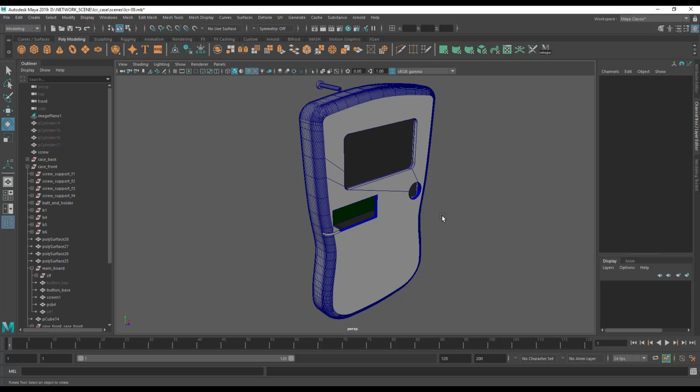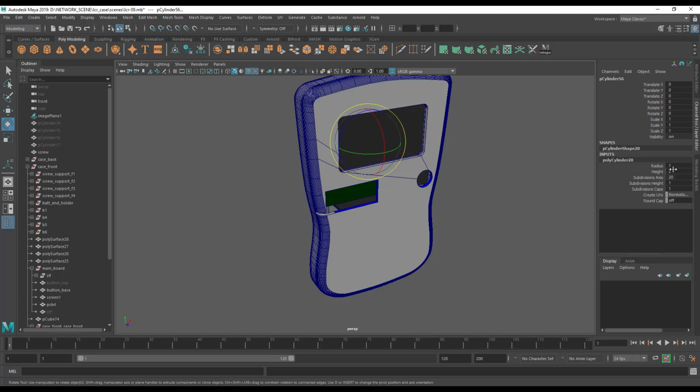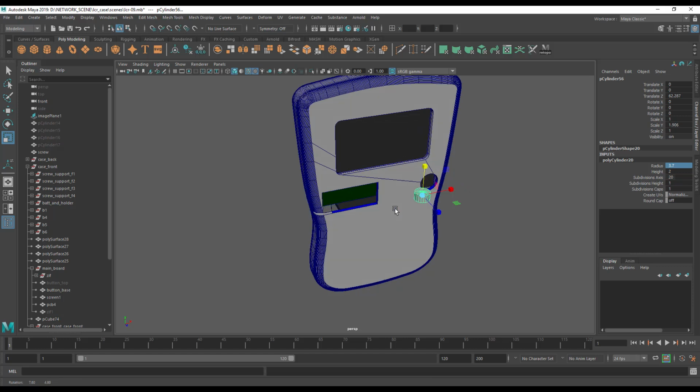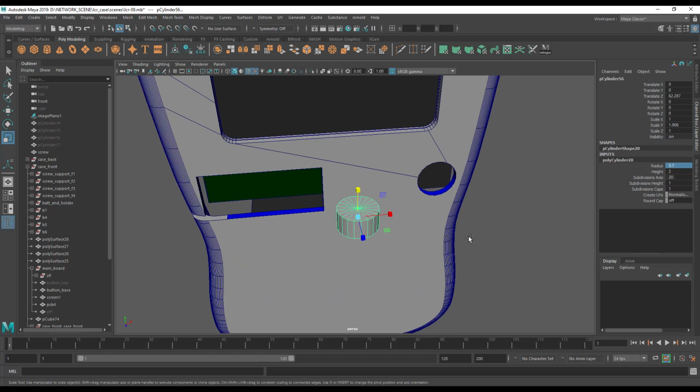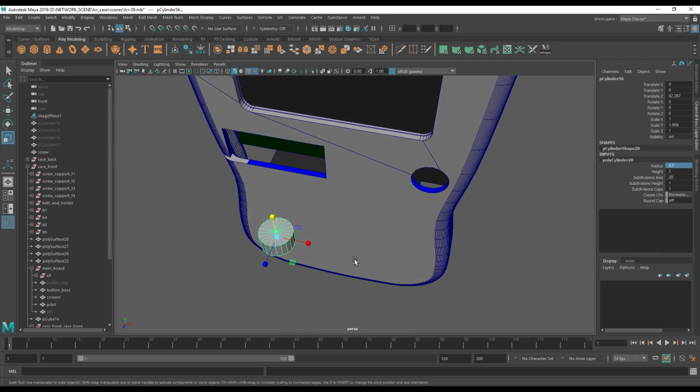And my binding posts, the things we looked at at the front of the tutorial, the things I'm going to use to connect to the inside gubbins of this, have a mounting hole size requirement of 3.7mm in the radius. So let's go ahead and make this 3.7. Okay, and that should be good enough. Now all we need to make sure is they're wide enough to use as Boolean objects, but they should be more than wide enough. Now I also need to create 2 more of these because I have 3 posts to go through the front of the case.